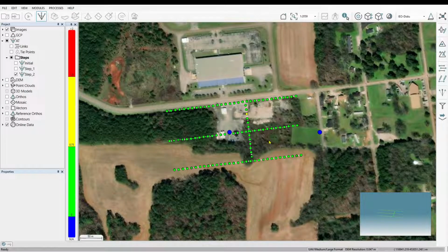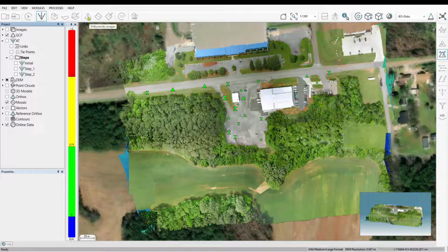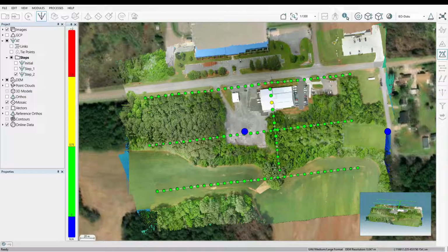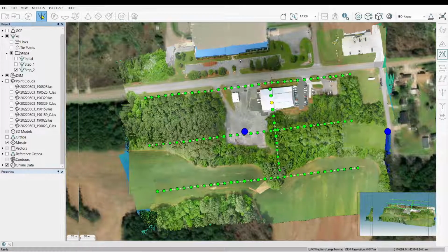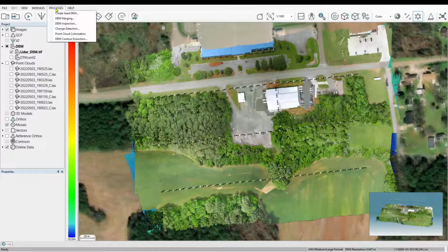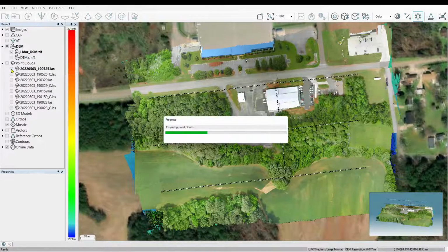So from that, you would then just go about your processing. I think we create our deliverables, which are the ortho photos and the mosaic. Of course, we can colorize the point clouds if we need to. I think I've got colorized point clouds in here. Yes, so you would go to, let me get out of AT. You would go to point cloud colorization, got one loaded here. So here's a regular LAS, and it'll take a second.